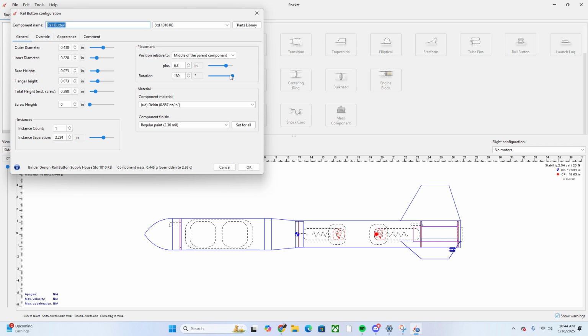So since in this case we can have a rail button around the center of gravity, you can either have it right here and add a spacer to both of them to clear the rail and not have this piece impede on your rail, or you can have no spacer on this one and one spacer on this one, and instead place that one up here. We could keep them down here for now.